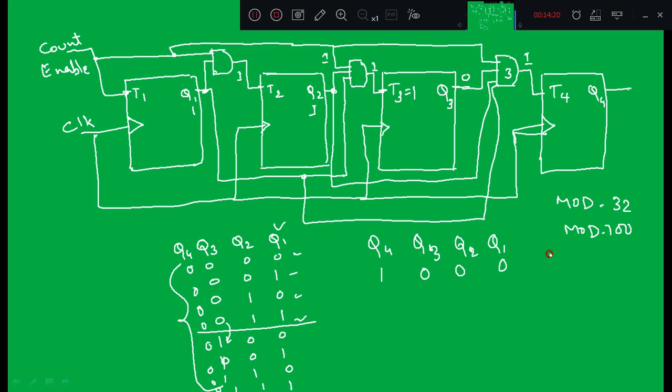So if I want to build a 5 input AND gate, I have to make use of one 4 input AND gate plus one 2 input AND gate, right? So it is not practically feasible, you can say. So that is the disadvantage of this circuit. So we will modify this same circuit, and we will overcome that disadvantage. In the next, modified circuit, I will discuss the same operation, but the circuit will be different. Okay, so how can I do that? That we will see in the next slide.